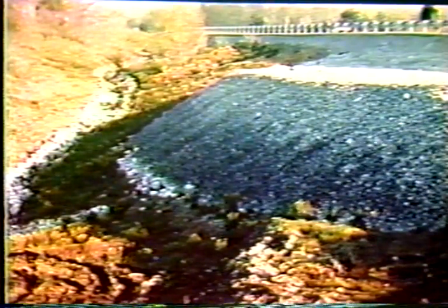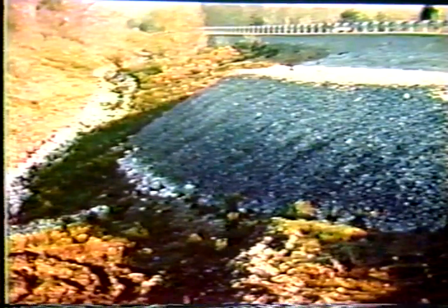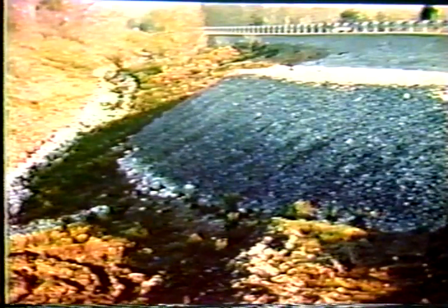Here's an example of the use of a berm on a highway. What I show this slide for is that there was a drainage ditch there, and they had to put a pipe under it, but they still managed to put the berm in. Now, I'd like to talk about a case history here for the next few slides where the berm didn't work. One reason it didn't work was because the geotechnical engineers were told not to make an investigation. They wanted a quick solution, and so they did the best they could.